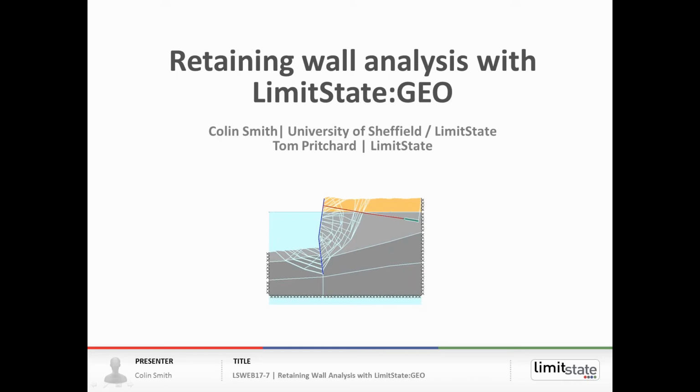Today's webinar concerns the modelling of retaining walls using LimitState GEO, and it will provide you with an overview of how you can use the software to undertake geotechnical stability analysis to rapidly determine the critical failure mechanism and also the margin of safety for a range of geotechnical problems, mainly involving structures such as gravity walls, cantilever walls, anchored or prop sheet pile walls.